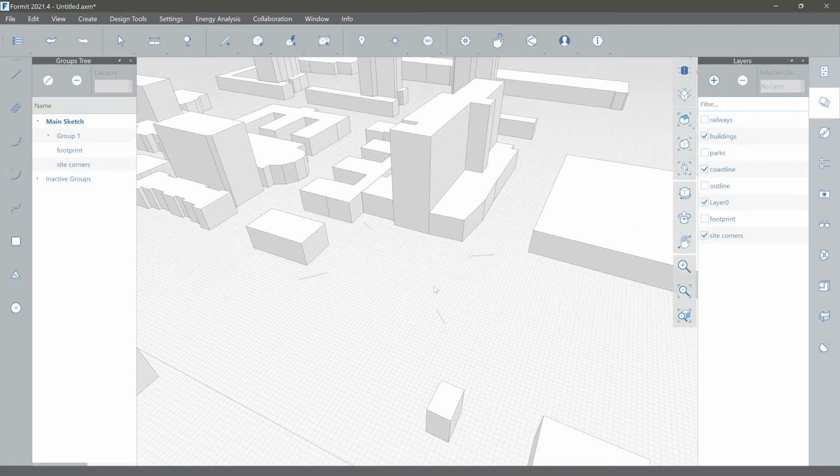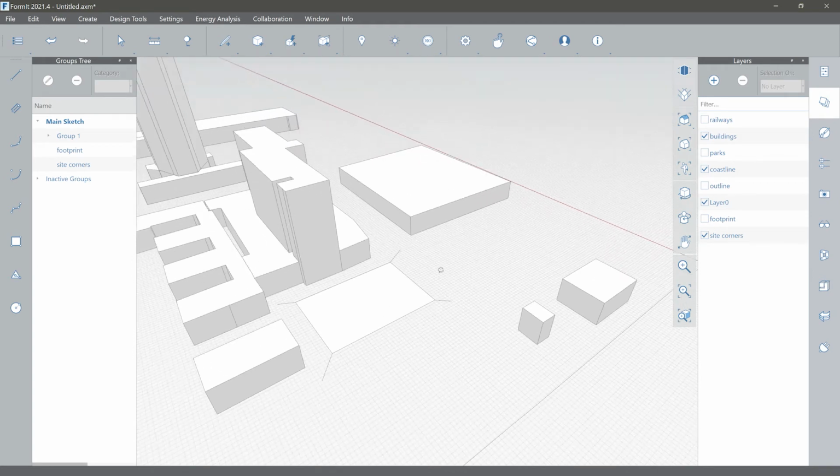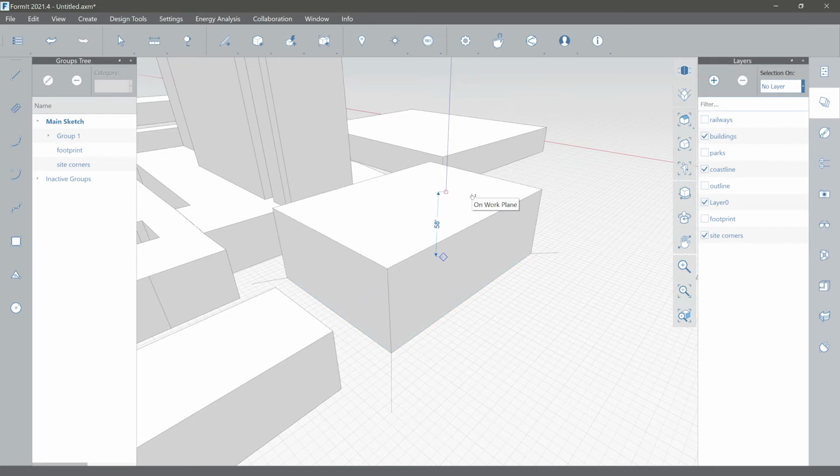So what we're going to do is make our first typical building for the second sequence in our diagram. I'm grabbing the rectangle tool, or R as the shortcut, and I'm going to grab the corners that I need. Now I'm going to extrude this up about 300 feet. It's a little bit fast, but to quickly activate the push-pull settings, you just click on a surface once to activate it, and then click on it again to get a point to move from.